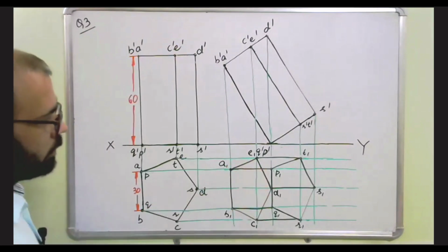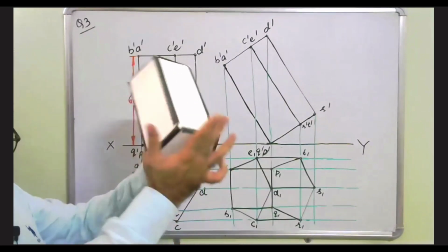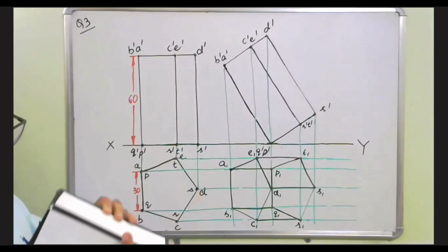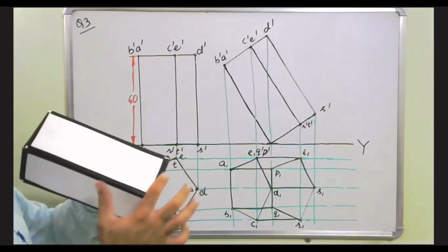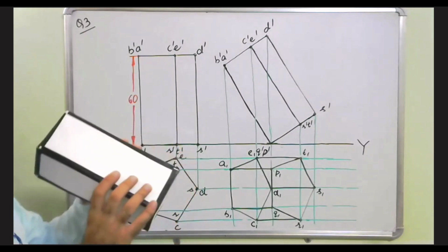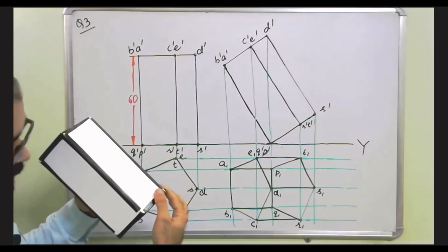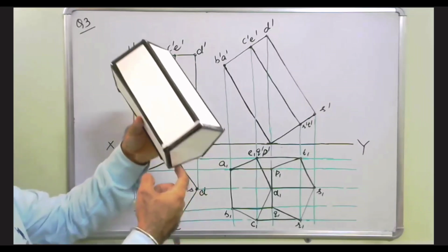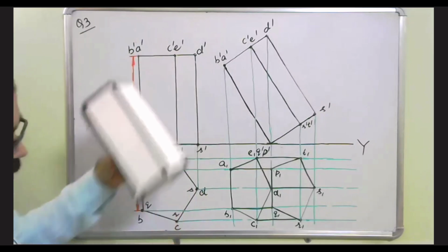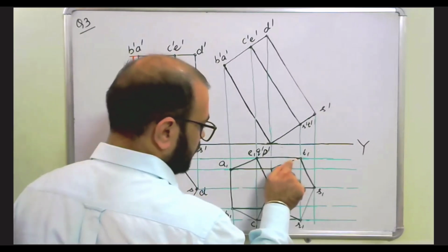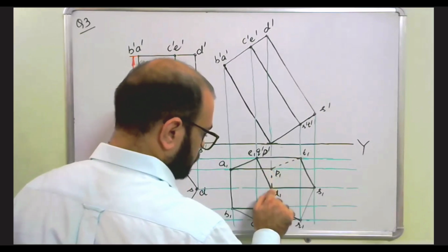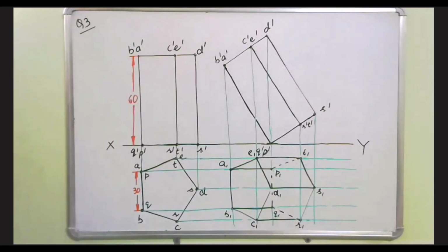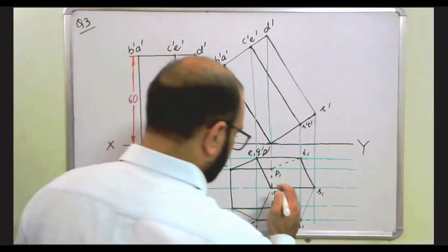So this is okay. But the base pentagon, this one, in the base pentagon only this edge and this edge, this edge and this edge, these two base edges only will be visible to you, and rest, this, this, and the other one, this one. So these three will not be visible from the top. So these will come out to be hidden lines. Right? So this is the first thing that will come in hidden.